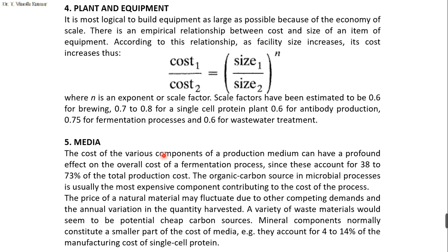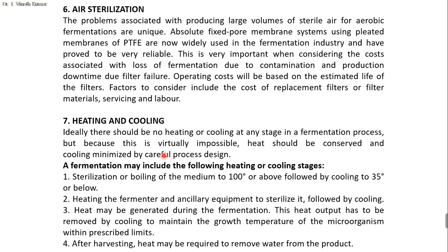the cost of the plant and the cost of operation that should be compensated, and fifth one is the cost of the media, and the air sterilization is also there, that will cost much, and you can use some of the parameters like PTFE filters for sterilization at a local level. And heating and cooling, preferably you can use the heating method instead of cooling, and if really the cooling is required, maybe you can use some natural cooling methods instead of refrigeration or otherwise cost consuming cooling methods. The fermentation you can do at the normal temperature, that is okay, but in the very cold condition, that may increase the cost.